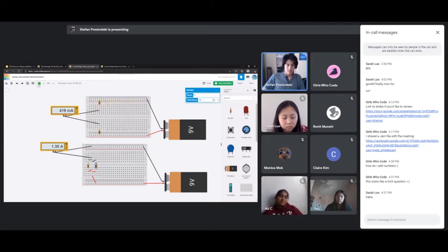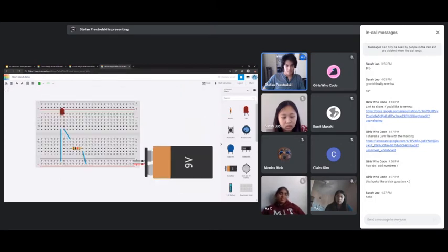And now here's something else. Here's one of those things that you just want to avoid. So you remember earlier that short circuit demo, right? You start this, the light bulb turns on. We have our power, it goes through the resistor, that turns on the light, and flows back to ground. Simple enough. But what if I add this little wire here? This wire will short circuit the system.